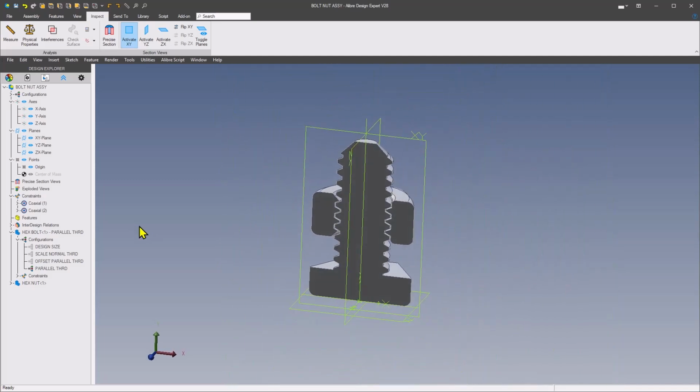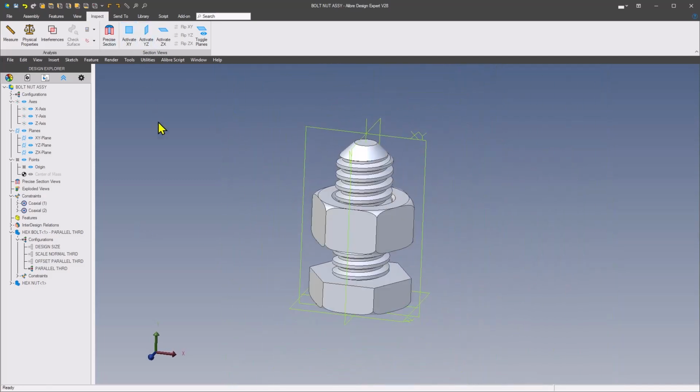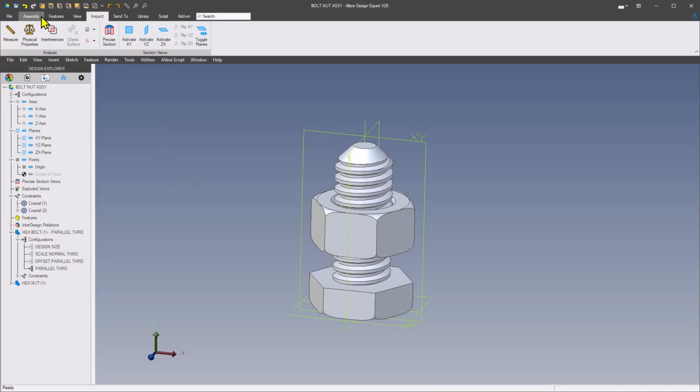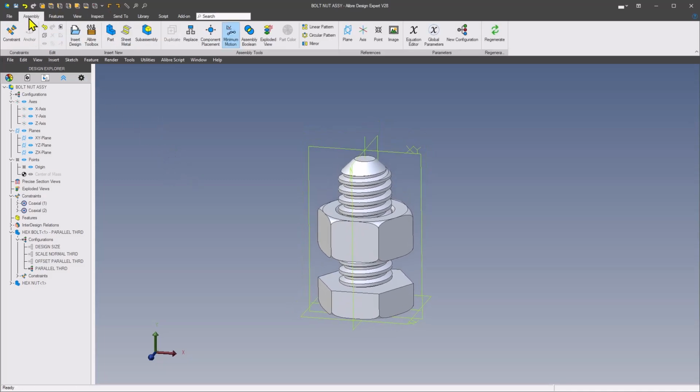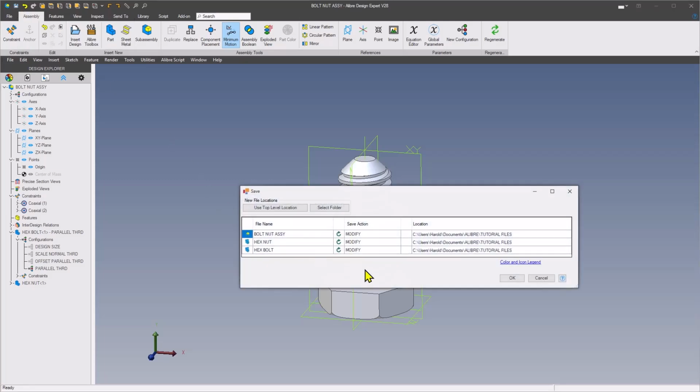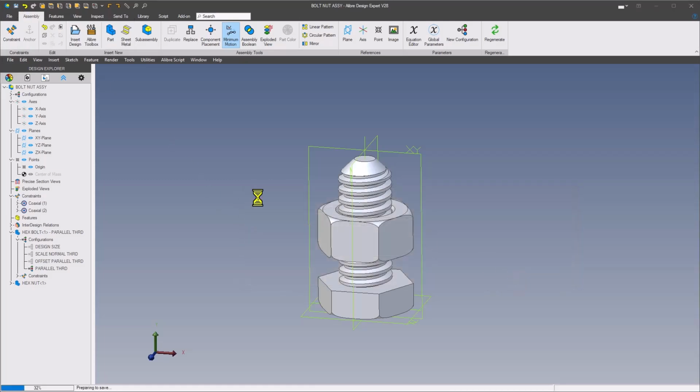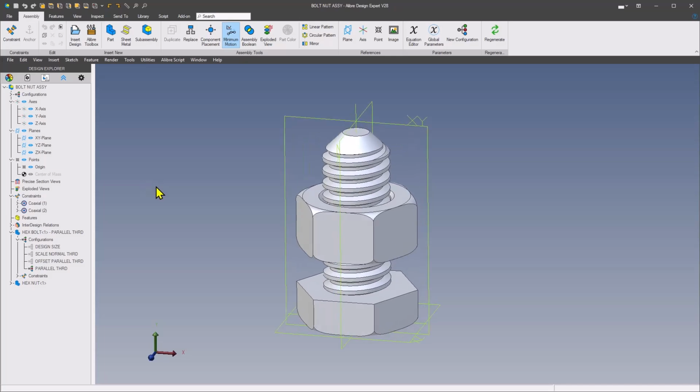So there's a couple of ways of creating the hex nut with clearance, and I guess it's a matter of whatever suits your fancy, whatever you feel comfortable doing. You've got a couple of methods of creating the offset thread for your Boolean to create clearance, and those adjustments can be made depending on what you need for your respective 3D printers.